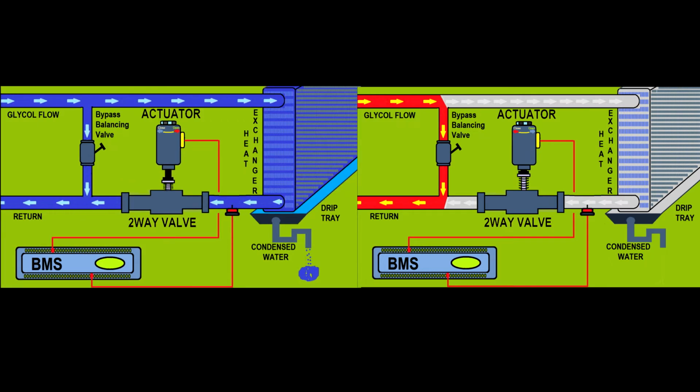Sometimes the temperature is okay, but as you'll see in this case, we want to remove moisture from the air. So how can we remove moisture? We have to run the heat exchanger below the air's dew point. So in this case, the heat exchanger will be very cold, and then we will have a side effect. The air gets very cold, and the premises will get very cold.